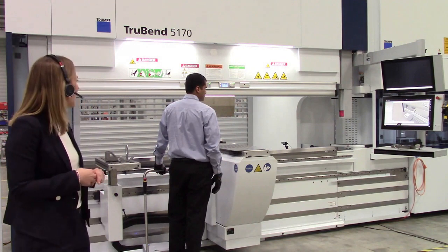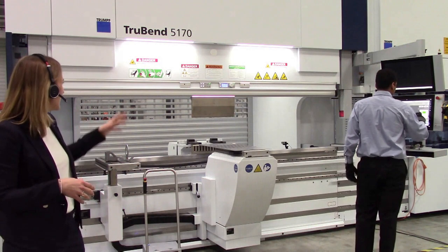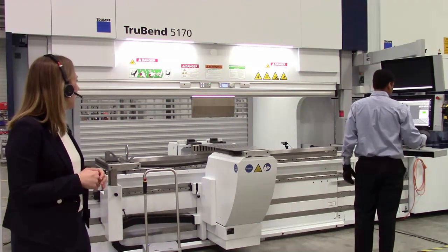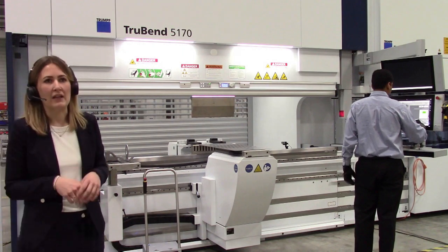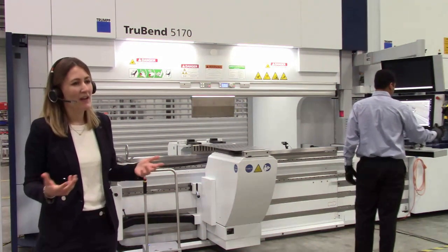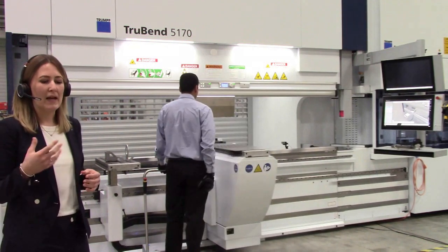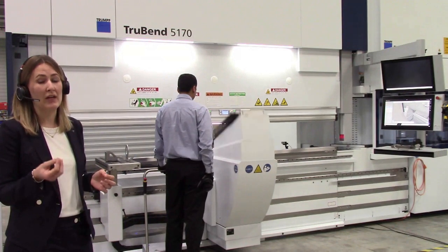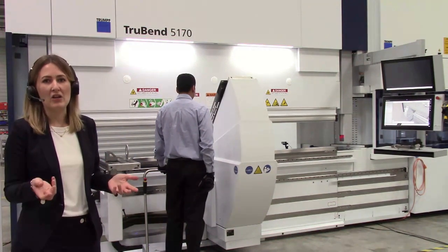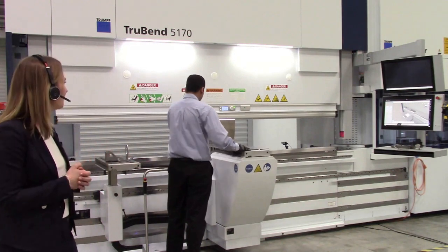So Anurag is bending a part here. You see it's a large, heavy part, and he is actually also using roll bend tooling on the lower die bed here. That is another nice feature to reduce your non-productive times, because that is suited for when you have holes very close to the bend line. So we will make sure that there are no deformations, and therefore, again, first part, good part.